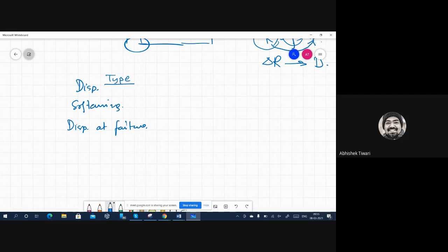So it is asking whether you are defining the damage evolution in terms of displacement of the element. Okay, so if I take a 2D element, then it is talking about either the displacement in this direction or in this direction, or net resultant displacement. So what should be the amount of displacement, and depending upon that, the failure is designed.